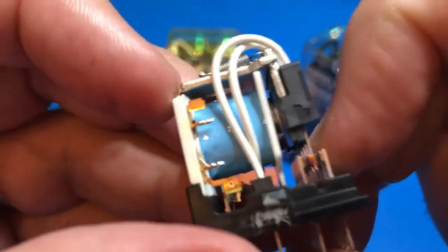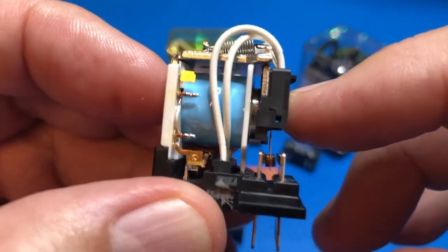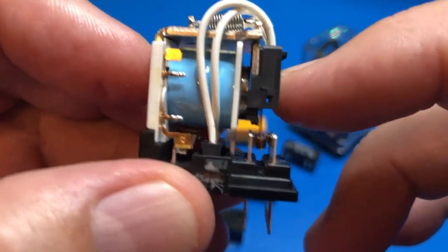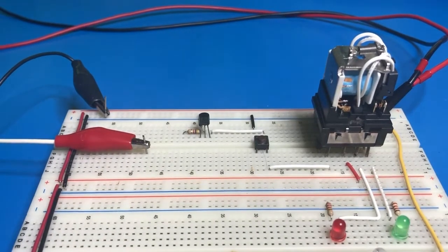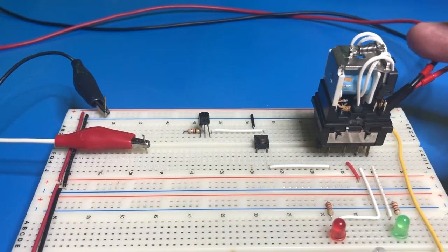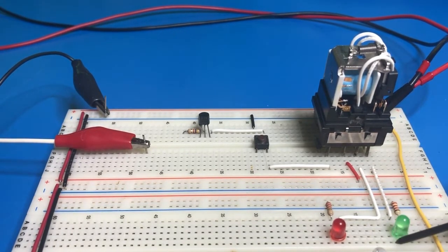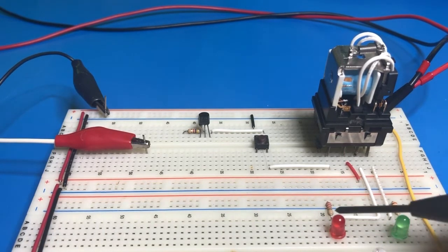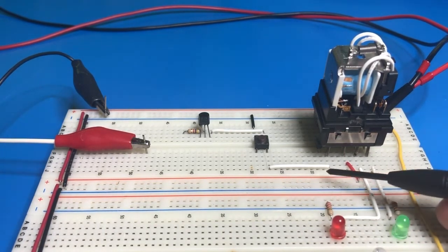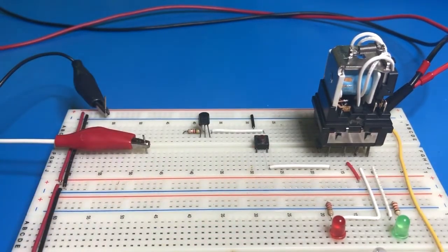Imagine, hundreds of these is how we can build a relay computer. And I will show you a little bit how they work. Let's see a relay working. What I have here is a bigger proto board, and instead of a battery, I have a power supply. On the relay, one of the contacts is connected to a green light, and the other one is connected to a red light, and the control winding is connected to this momentary push button.